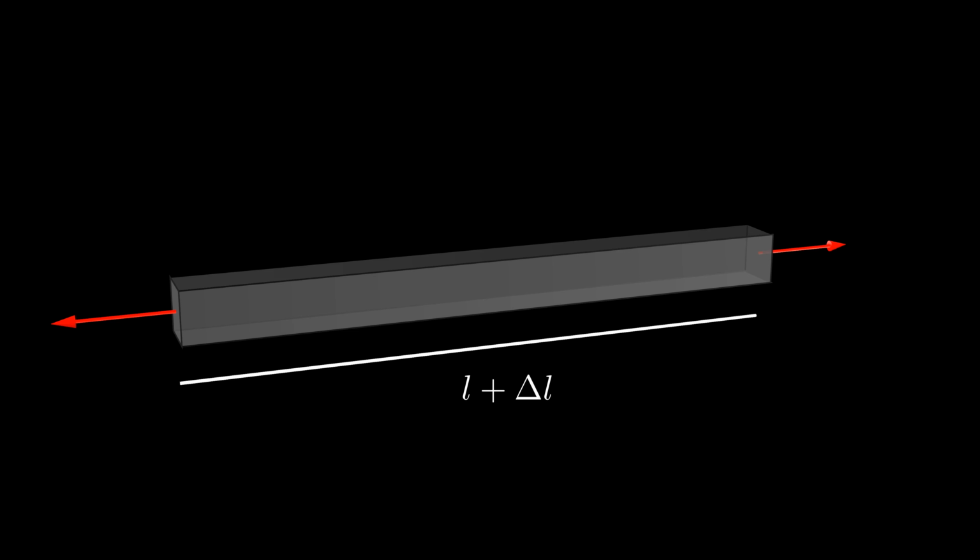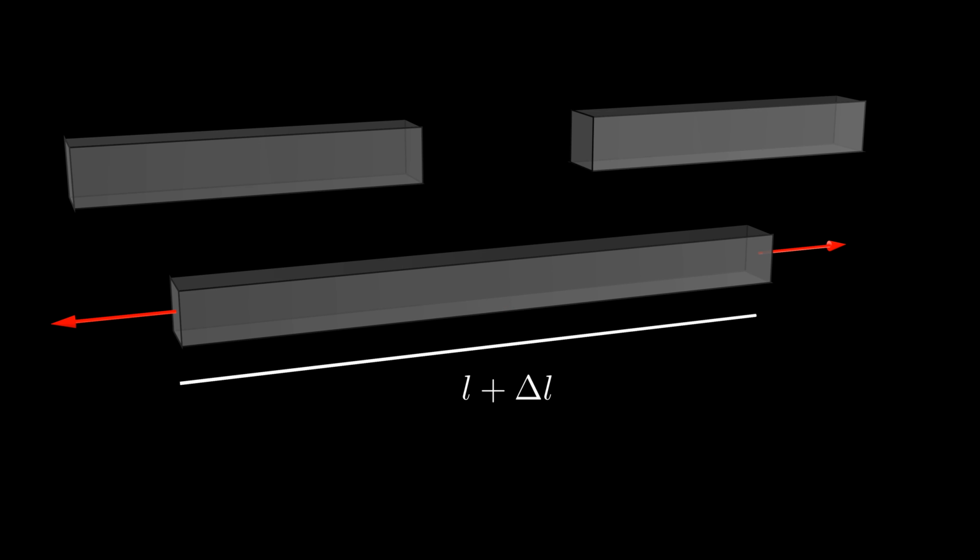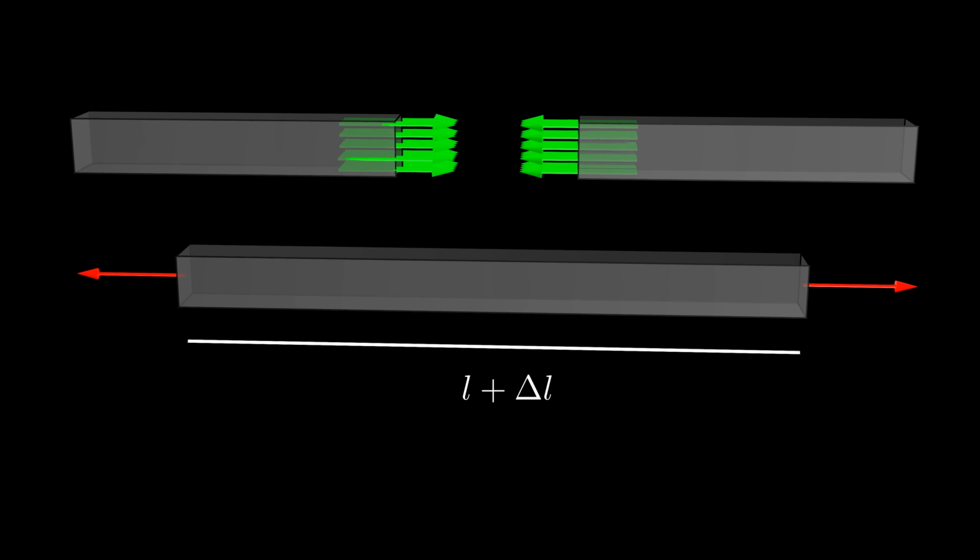The bar's tendency to stay in its current position and resist deformation will be realized by the action of internal forces. These internal forces counteract the external loads applied to the bar, striving to maintain the equilibrium and stability of the structure. If we mentally cut the loaded bar in the middle, we can visualize the forces that are holding the bar together at the center.